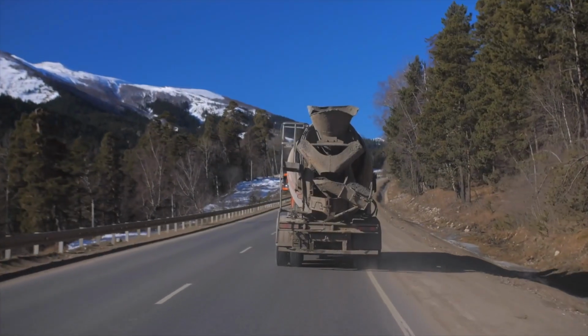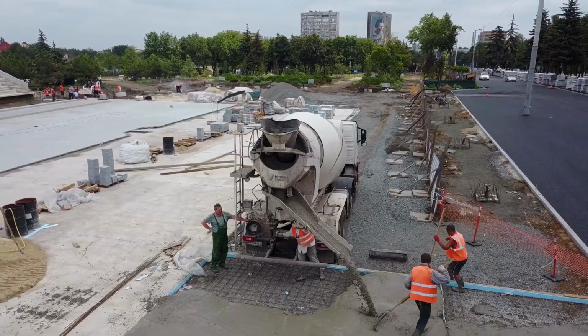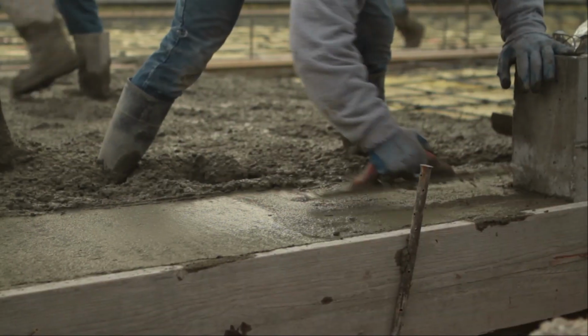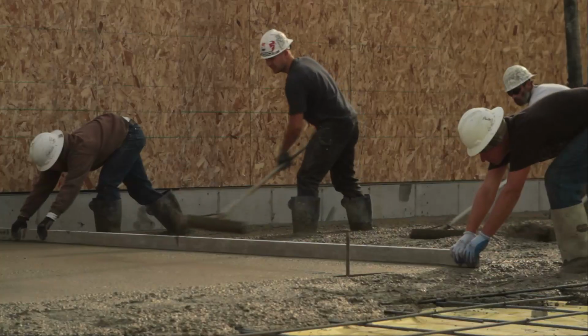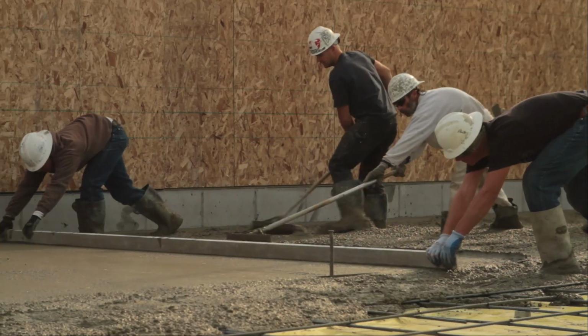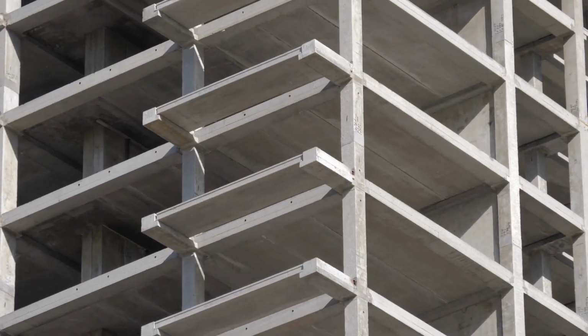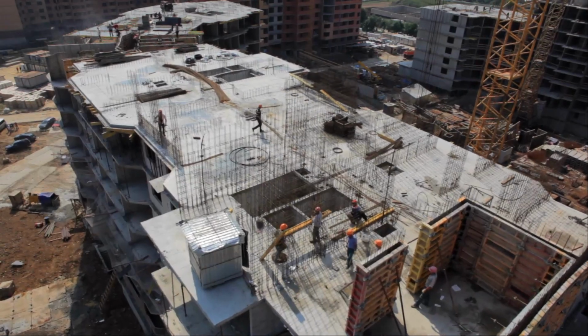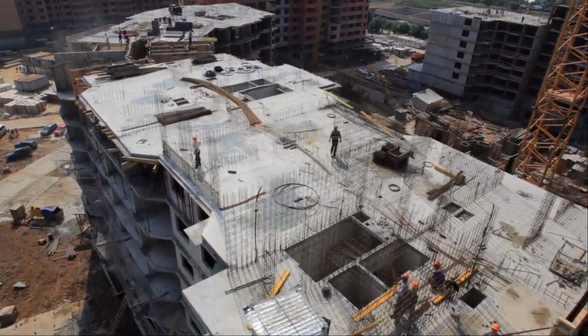Admixtures are added to adjust setting time, workability, and properties like strength. The freshly mixed concrete is transported to construction sites, carefully placed, and compacted into forms or molds. Proper curing by maintaining the right moisture and temperature is essential to allow full hydration of the cement and gradual strength gain in the concrete. The versatility of concrete, enabled by the controlled production of its constituent cement, makes it the most widely used building material in the world today.